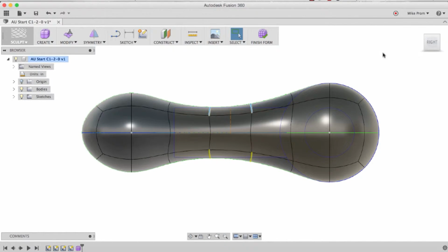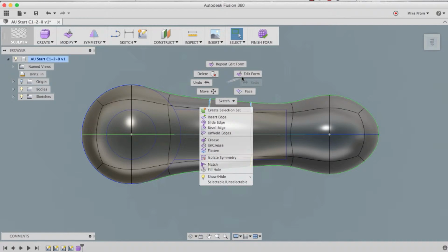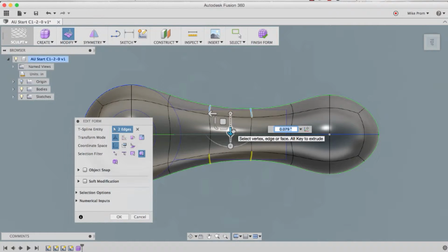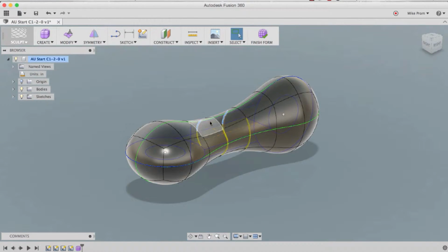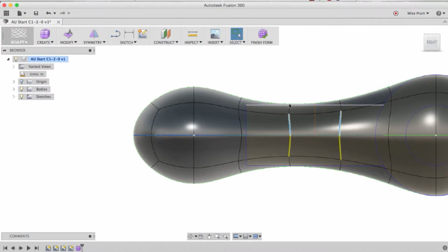This will allow me to model different techniques with that same original sketch and have them have similar parameters or size. I use my view cube to rotate between the different planes when I want to make sure the two sides have the same distance, and looking at those sketches again to line up with the thickness. With this complete, I can concentrate on the front side or the left quad ball. The right side I'm going to use a trim feature later, so for now I'm just concerned about the left side.